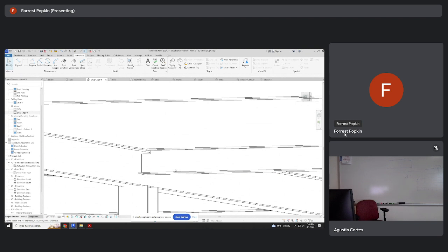So were you here at the guest lecture last week? One of the things we talked about was when you hand over building information modeling. This is an example of something that doesn't get modeled in every single connection because it would be mind-numbing to do that, right? But some people have this expectation because they're handed over a Revit model that if I put it on one part of my drawing, it should show up here. Well, I just got done telling you that's the reality. You have detail things and you have model things, and they're not always the same.